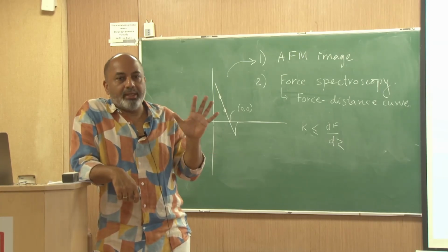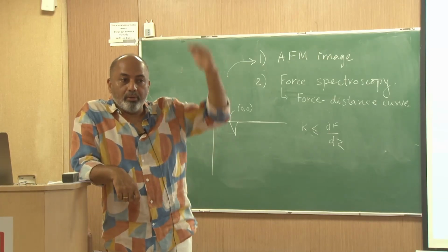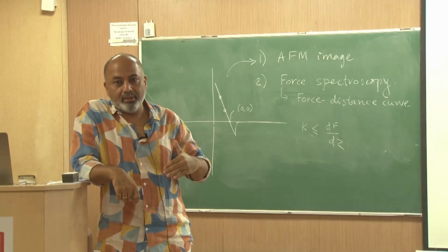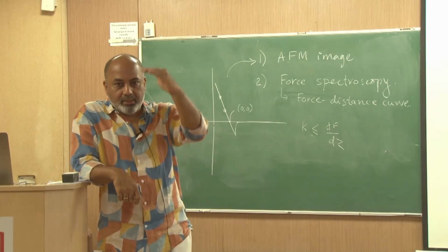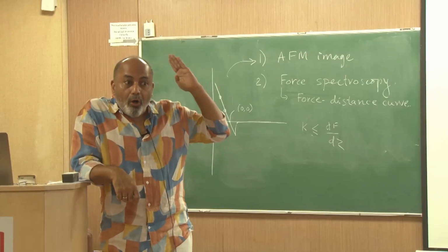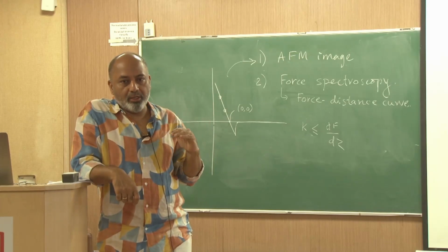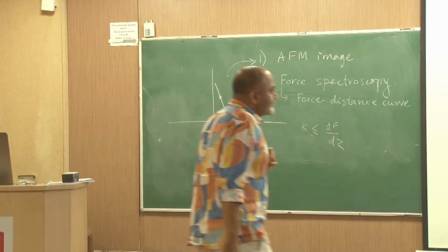It does not do anything, it just measures temperature, and as it goes above a certain threshold, it will stop cooling or start cooling, okay. And so this creates an oscillating temperature in a room. We do not want that, we want it all the time at the same fixed value, and this is done through a PID controller. So, how is that done?